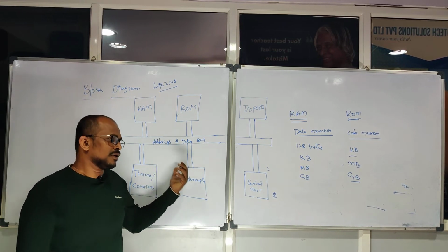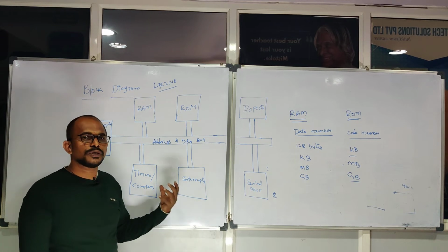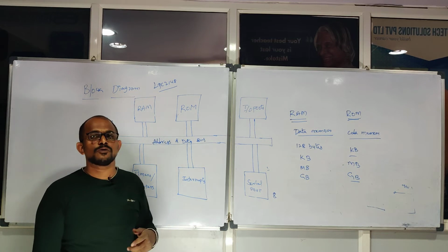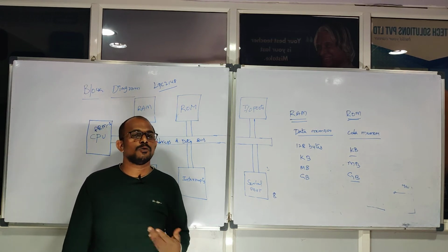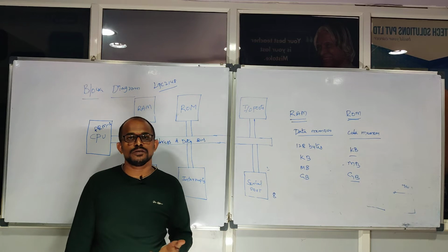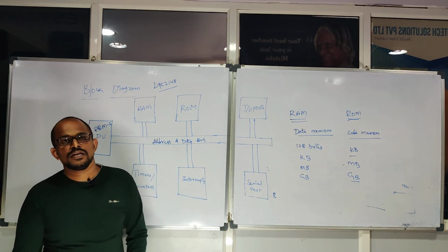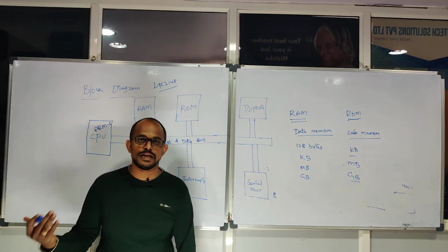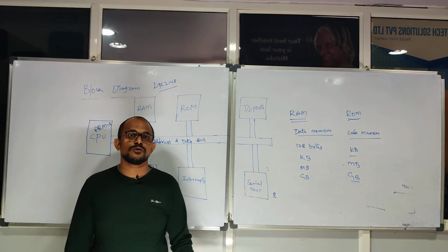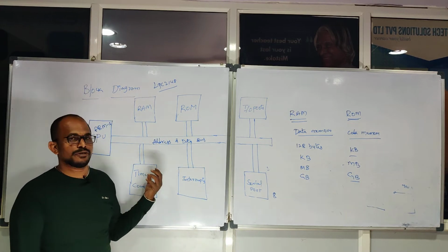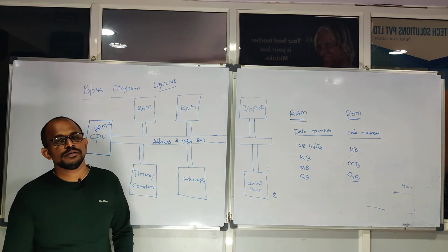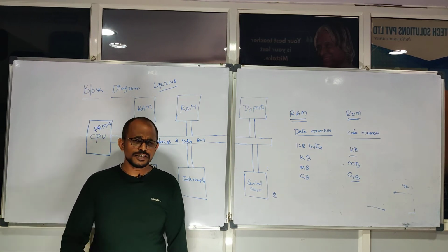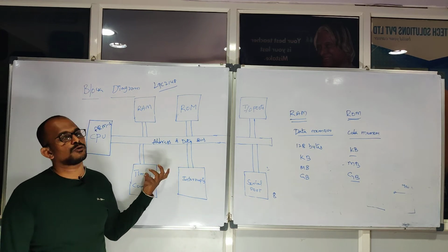So if you are looking for accurate time delays, you can use the feature from the microcontroller timers. Any microcontroller will give some number of timers, maybe 1 timer, 2 timers, 3 timers, 4 timers, depending on the controller family. Whether you are dealing with the PIC family, ARM family, LPC family or STM, every microcontroller comes with some standard timers. Timers are also measured by bit capacity: 8-bit timer, 16-bit timer, 32-bit timer. We will see more in depth while doing applications with the microcontroller.